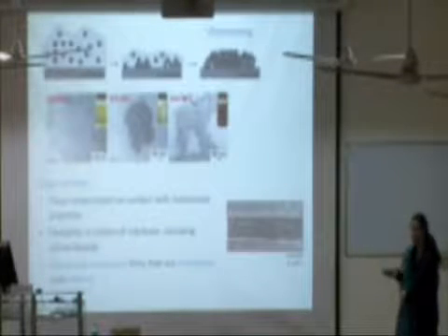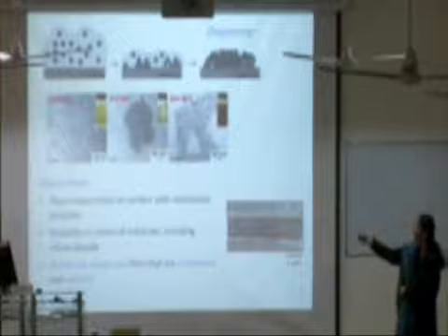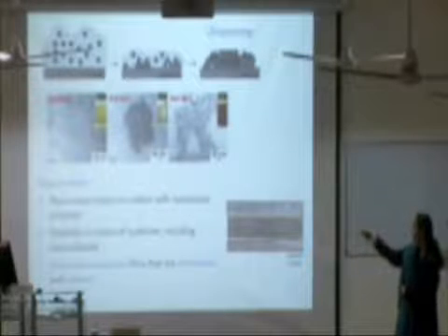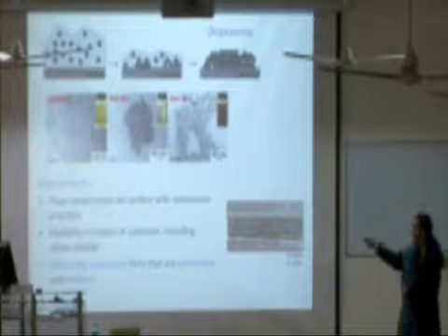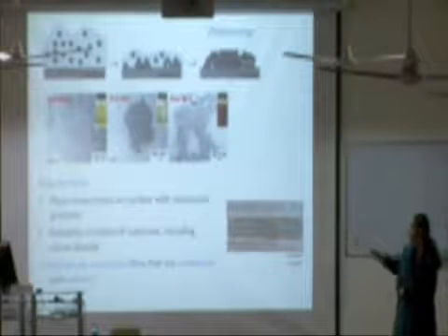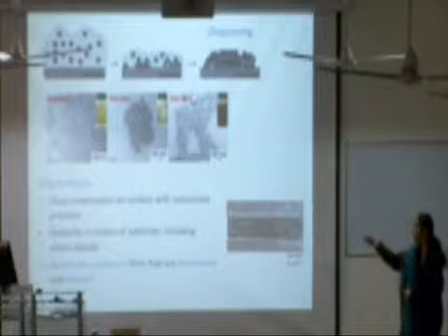So I now go back to the colloidal quantum dots that I described in the beginning. Here I show you cadmium sulfide, zinc sulfide, and lead sulfide quantum dots. They've been fabricated in these vials, and they're different colors because the band gaps are different. And these figures here are the transmission electron microscopy, or TEM, images of these dots, and this is a single monolayer.